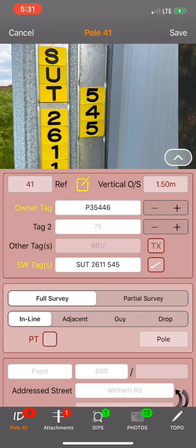Then every time you take a measurement with your laser on your tripod, you come back to that point if you have to restart your calculations. Typically, what used to happen is people would take a shot from the base of the pole rather than a base offset, and they would be way off because of the foliage down there. And then if they had to restart their shots, they would end up taking a starting point at a different point because they can't see through all that brush.